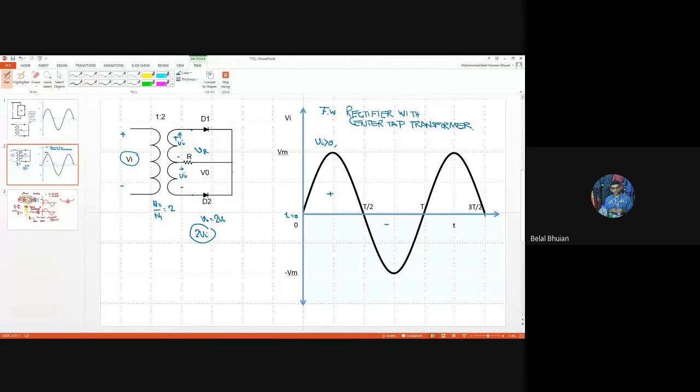Now, for the lower part of the circuit, we can see the positive terminal of the signal source is connected to the N side, and the negative terminal is connected to the P side. So this appears to be reverse bias. So it is reverse biased, which means that part of the circuit is not working for this positive voltage.